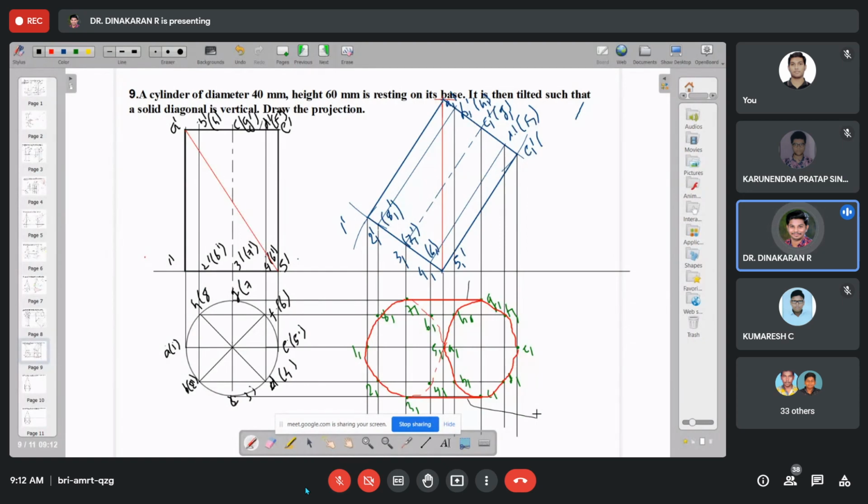For prism and pyramid, the longer edge, shorter edge, slant edge or any one of the ways will be visible. So for a cylinder and a cone you just draw the outside borders around. No need to draw the inside thick lines. Okay, this problem is solved.